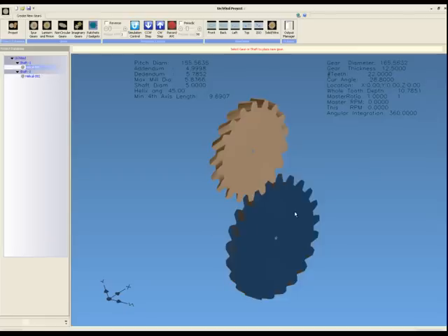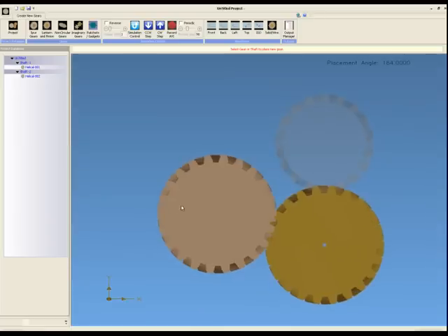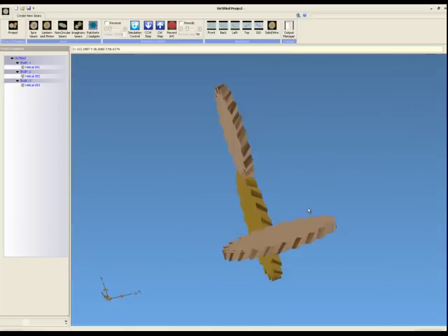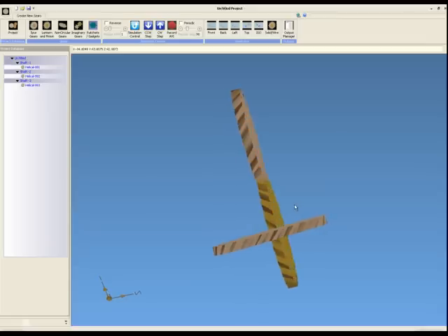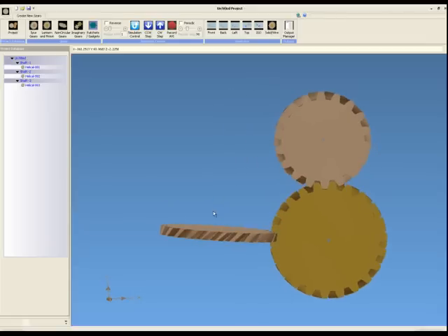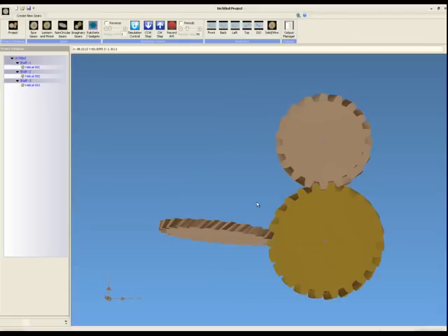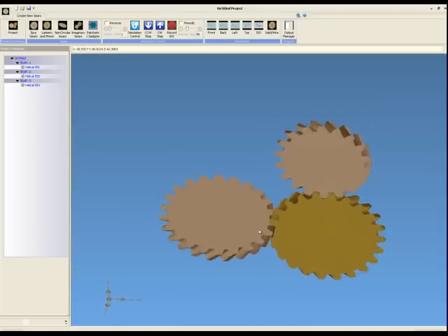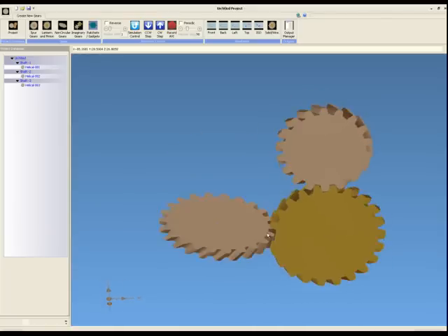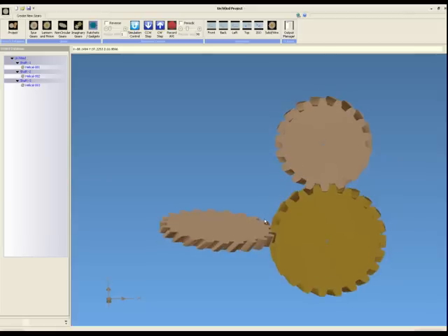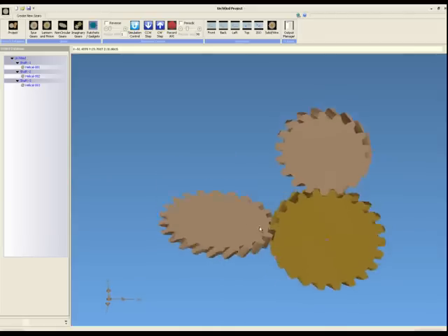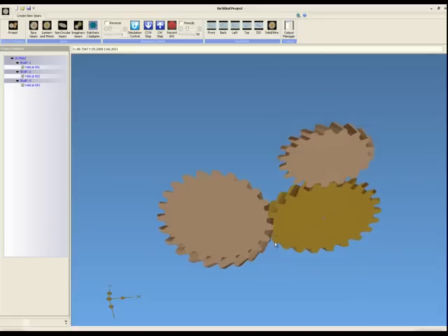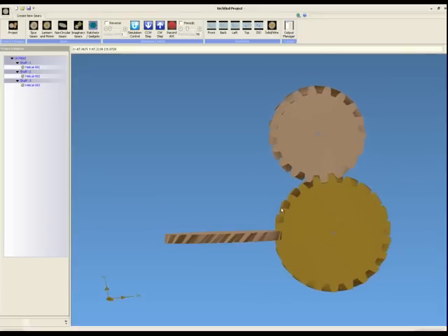The system will take this information, and when we roll our gear around and place it, you'll notice that one gear is now sitting 90 degrees opposed to the other in a transaxial plane. This is because if you use two helicals of the same handedness, they will rotate to a shaft angle which is equal to the sum of the two helicals. Since both of these gears were 45-degree helicals, they create a 90-degree shaft offset.